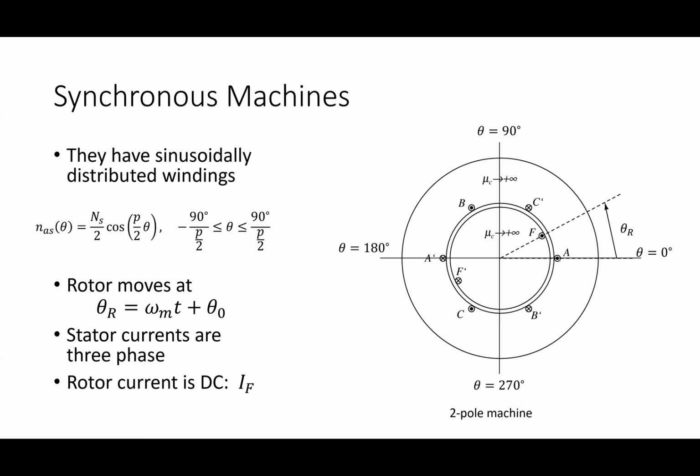So in other words, let's do coil A here. I always look at A. What does it mean when I have the circle? What's the current doing? Coming out, and when it's an X, it's going in, right? So it would go around the air gap in that counterclockwise direction, coming across the air gap along the top. If I were to go all the way around the air gap, it would look like that, and then it would be shooting across the air gap towards the stator on the other side.